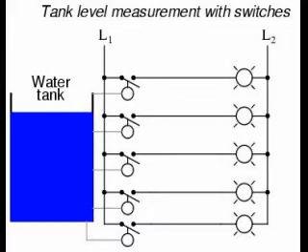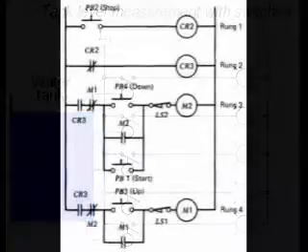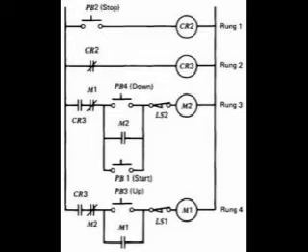Ladder diagrams are commonly used to document electrical control circuits. They may include all kinds of control switches. The switches or inputs are on the left side of the diagram. The devices being controlled or outputs are on the right side of the diagram. The two vertical lines represent the two power supply lines, either direct current DC or alternating current AC.